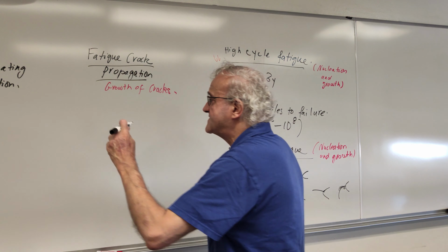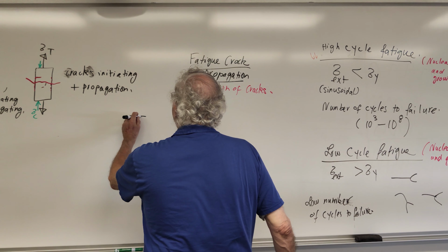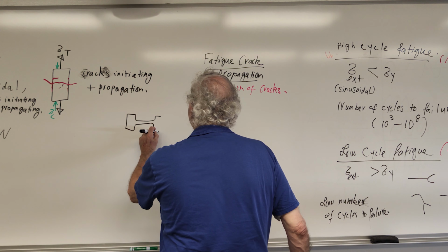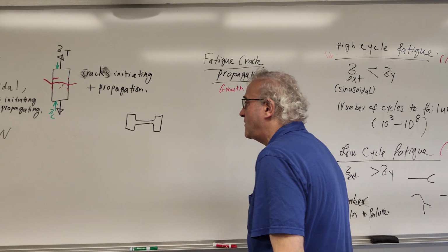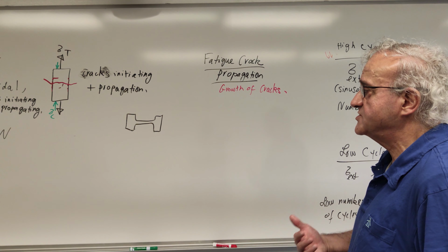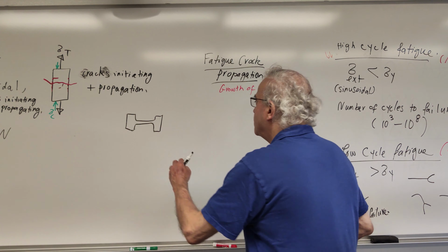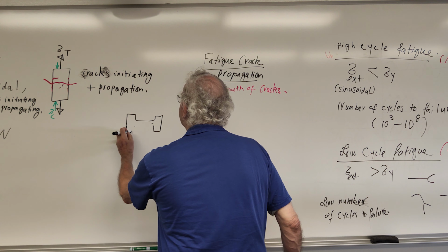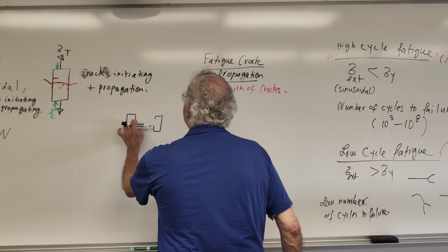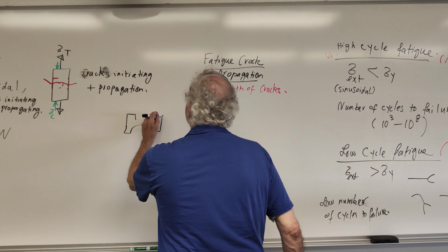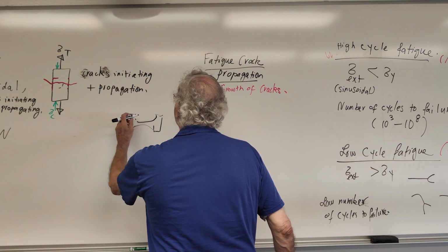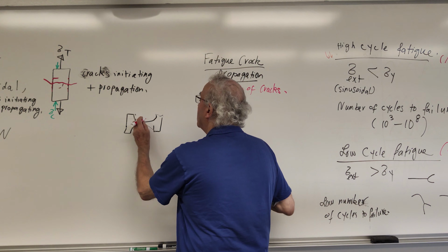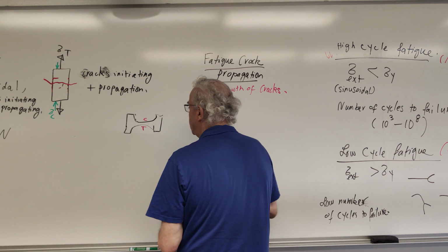But the idea is when you get the sample, you're going to expose it to R equals -1, a continuous change in tension and compression. At the beginning, let me try to draw it, you're going to have compression here and tension here.